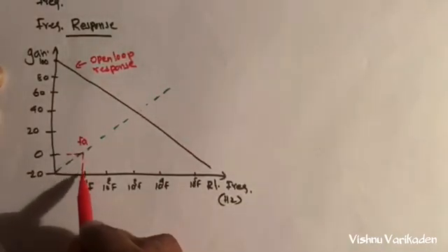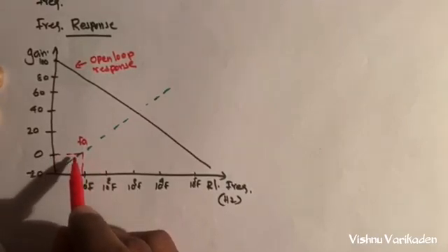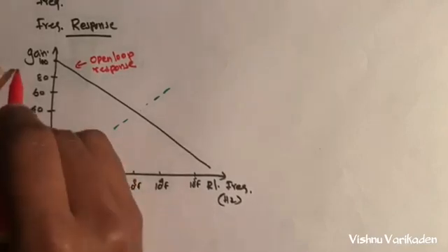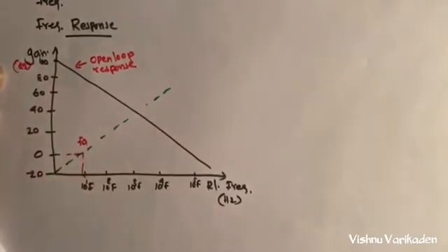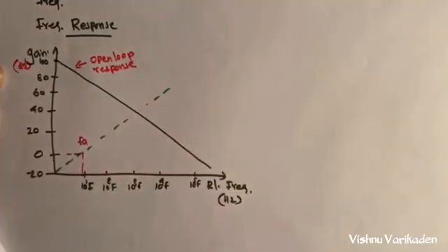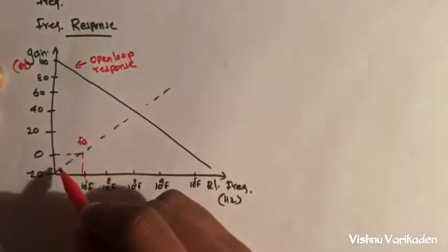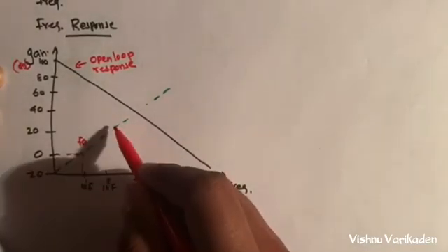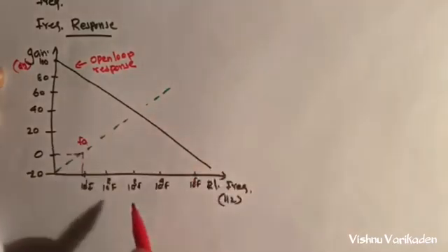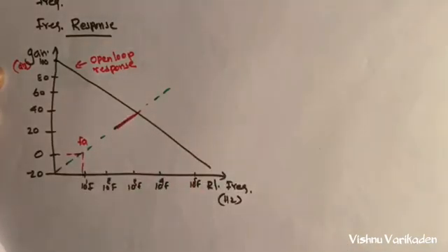Whenever the frequency is equal to fa, the gain becomes 0, or 0 dB. If we further increase the frequency in the ideal differentiator, the gain is going to be very high, increasing at plus 20 dB per decade. With the gain increasing so much, fluctuations and stability problems happen.